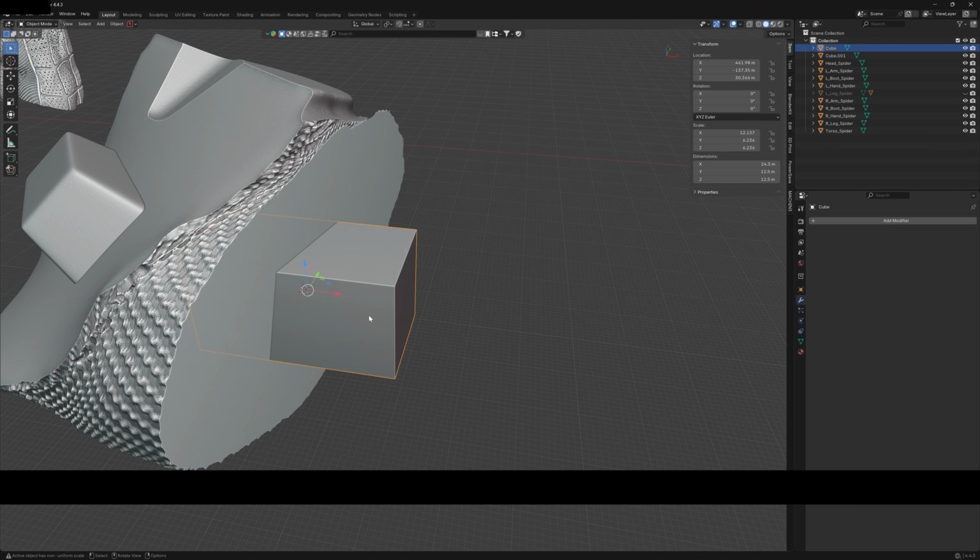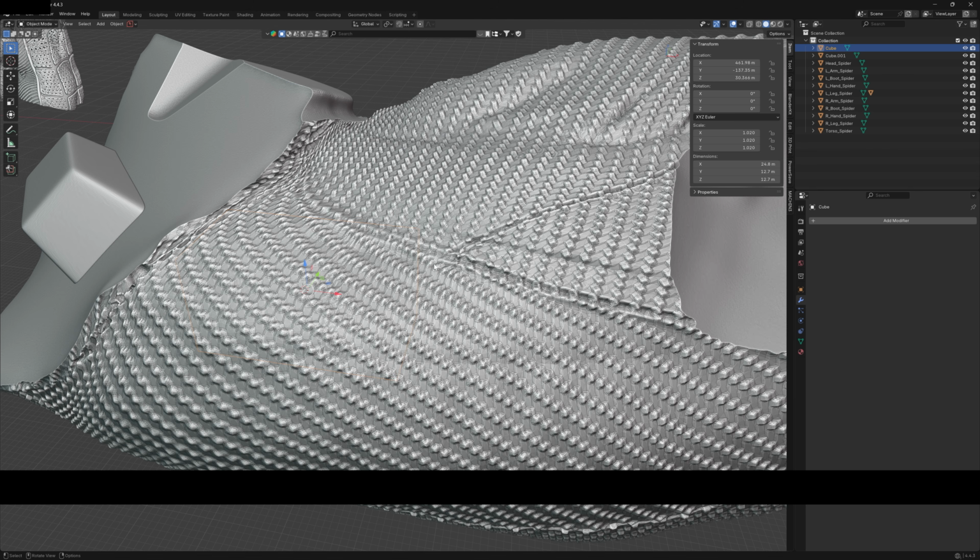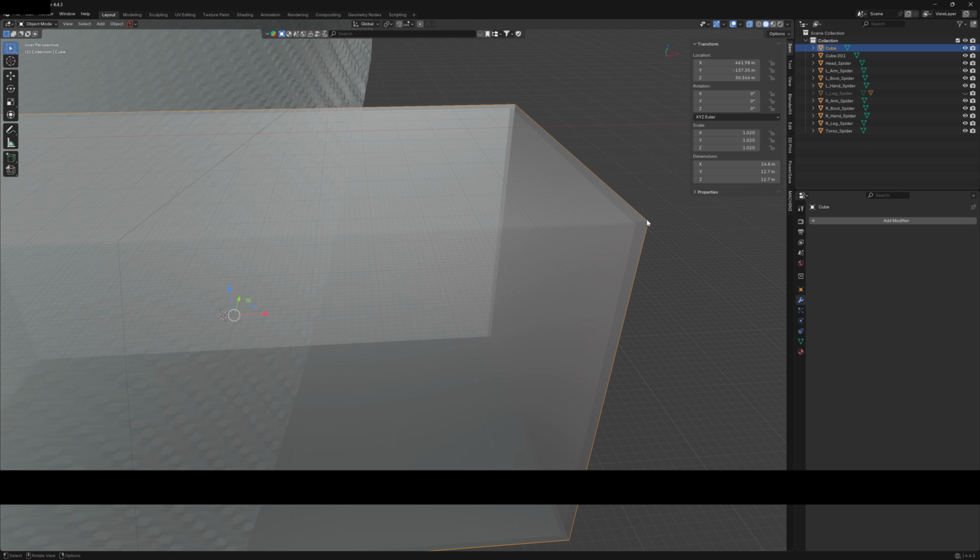And then if you notice me just stretching it around earlier, what you want to do is press Control A to apply scale. This resets everything to 1 or 100%. So if I were to go 1.02, and then if you watch the square, when I press enter, it's gone slightly bigger. So that's going to hopefully give you plenty of room. You can see the tolerance there.